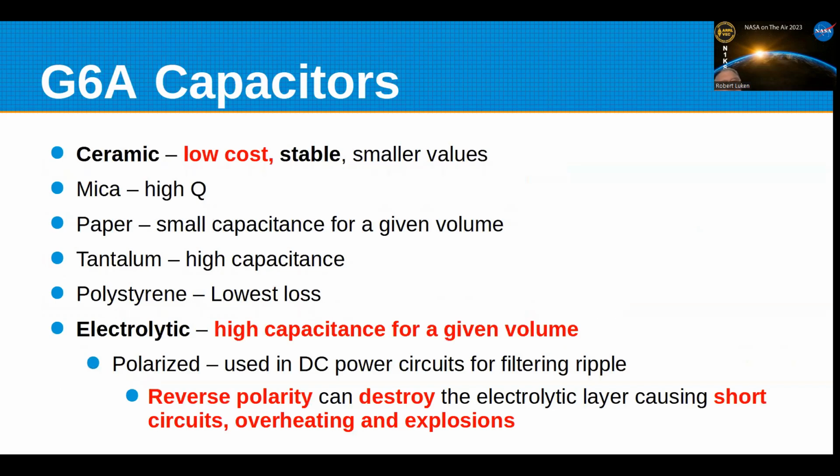Capacitors. The only thing they want you to know about capacitors, and there's a lot, is that ceramic capacitors are probably the majority of ones that are used, because they're very low cost, a very simple device to make. They're pretty stable.